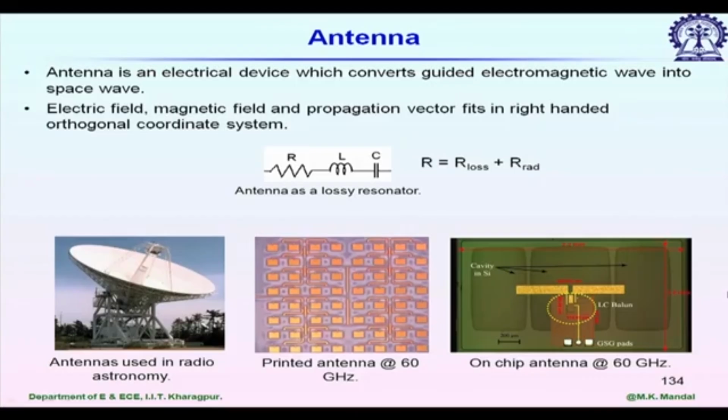When we do so, we of course face some problems. You can identify there are some cavities. This particular antenna is designed on a silicon substrate, and in silicon we face the problem of surface waves. To avoid that, people use an air cavity just below this antenna, which will improve the gain of the antenna.